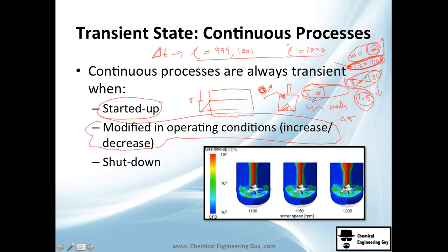So this state, it's going to be the transient state, because we are revamping, we're increasing our production, and therefore we need to increase this. You will see later in automation and control processes that you cannot just say, okay, just drop it and instantly it will turn to the desired values. No, actually there's a huge problem here in the chemical industry. You need to wait for the variables to set. So if you just say, okay, increase it by 50%, you're probably going to have problems, guys.